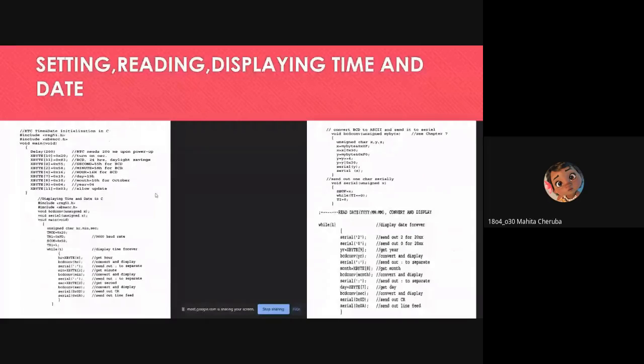So these values are going to get converted into ASCII form. To convert to ASCII form, what we do is we AND it and then we OR it. This is to separate the bits into lower bits and higher bits, mask it, and then we are going to use a right shift operator. And after we get the information from that, we are sending it to